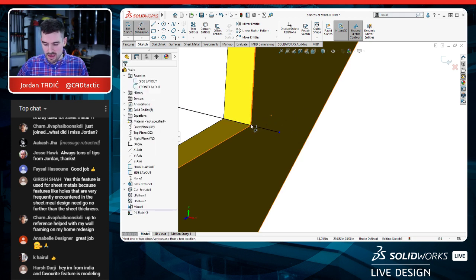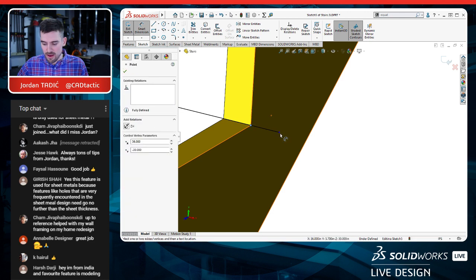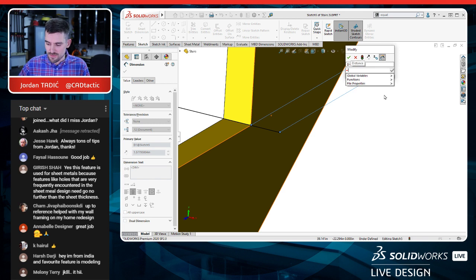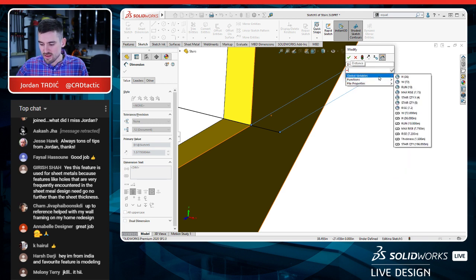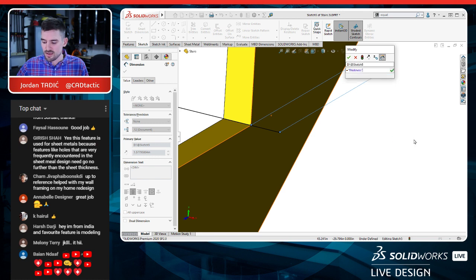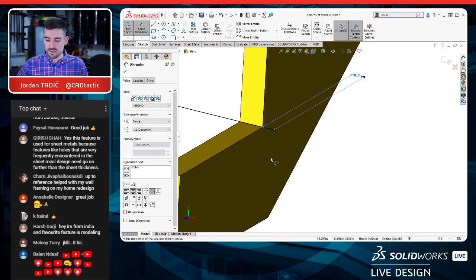And now within this sketch, I could just add a dimension from that point to that point, and I'll put this off in the white area so we can see. Let's just make that equal to maybe the thickness. So check that out. While you're filling out an equation, you can reference all your variables. This is going to be linked to the thickness, which is down here. Let's say divide by 2. So that will end up calculating to 3/4 of an inch.